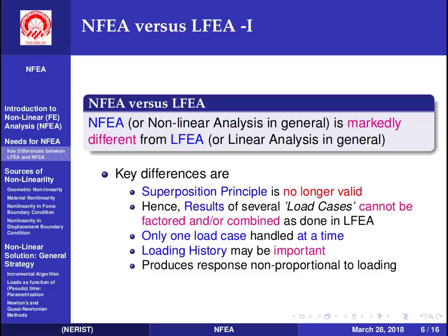In case of linear analysis, since the system is linear, we can apply the superposition principle, and thus we can superpose the analysis results from different load cases, whereas this cannot be done in nonlinear analysis because the superposition principle does not remain valid in a nonlinear case, and therefore only one load case can be handled at a time in a nonlinear analysis.